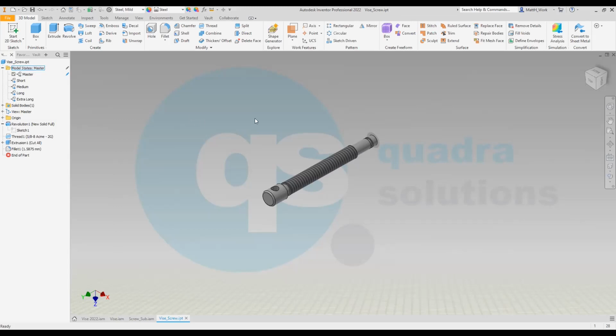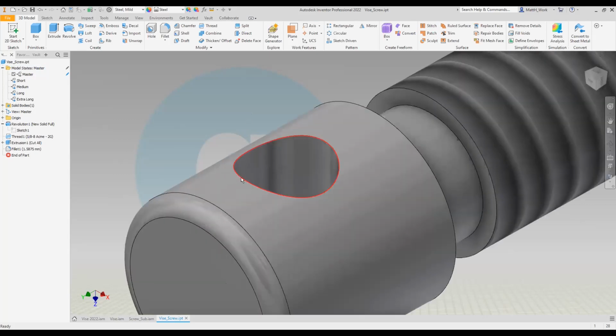One little bit of warning, if anybody out there is an iPart iAssembly user, factory scope and member scope. When you're on member scope, any edits you make to this particular occurrence don't occur to the others, so that you can create unique features on this occurrence that don't occur everywhere. If I need a chamfer on the edge of that hole everywhere, I'll use factory scope.